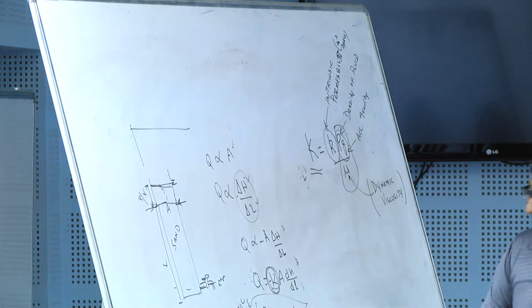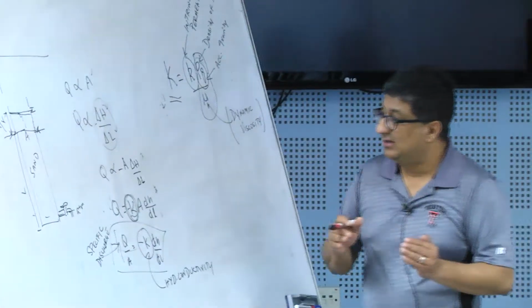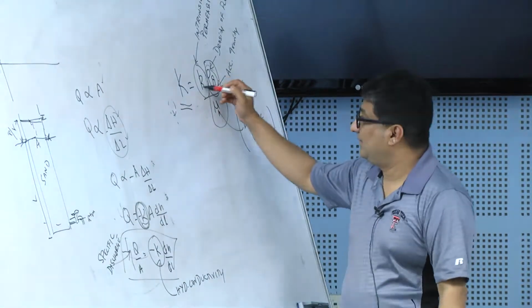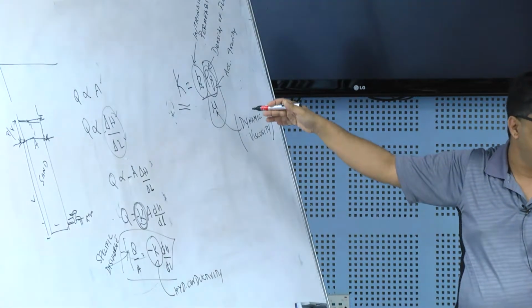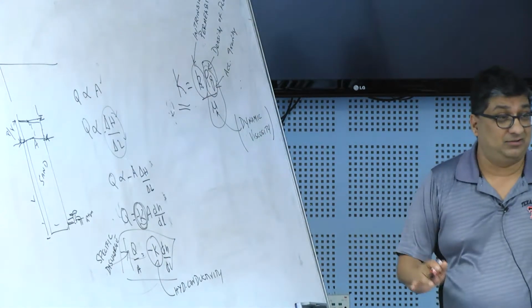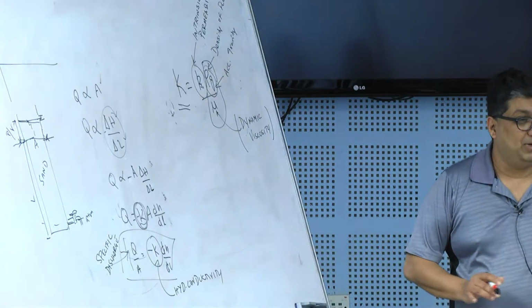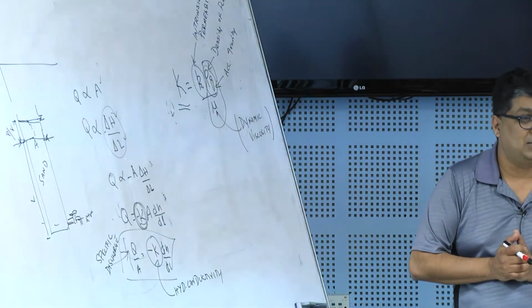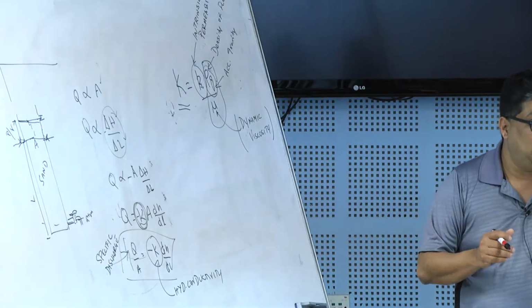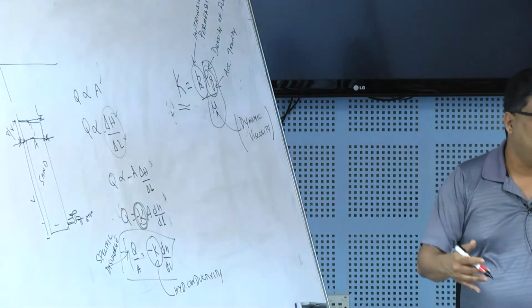So when he measured this hydraulic conductivity, that hydraulic conductivity was a function of, our fluid was the same, so we don't worry about fluid properties. For us, it's water. The density of water and viscosity of water don't change as much. They change a little bit with temperature, but within the normal ranges of what we see, it doesn't change much. So water is an incompressible fluid and works great for us. But this K does change with the geology.